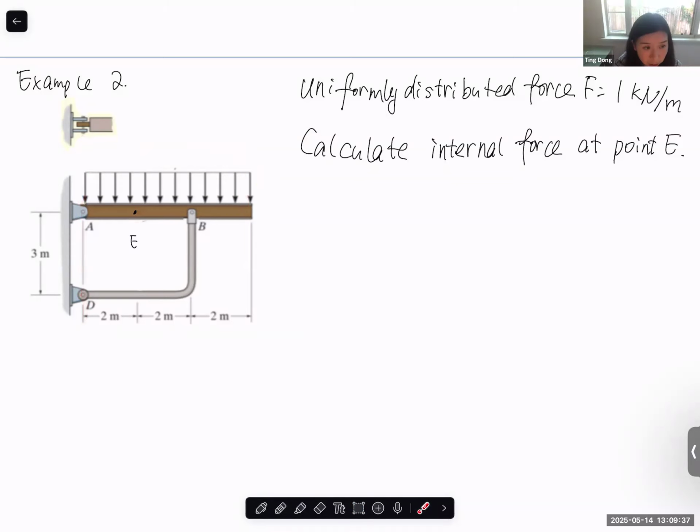It's the same thing. It's also the same if you do the free body diagram of this horizontal beam, because the force applied at B has a given direction, just the magnitude is unknown. So same thing, we have three unknowns and three equations. It's the same. So let's do it this way. Separate the structure from point A, the pin joint, and separate the structure from point B.